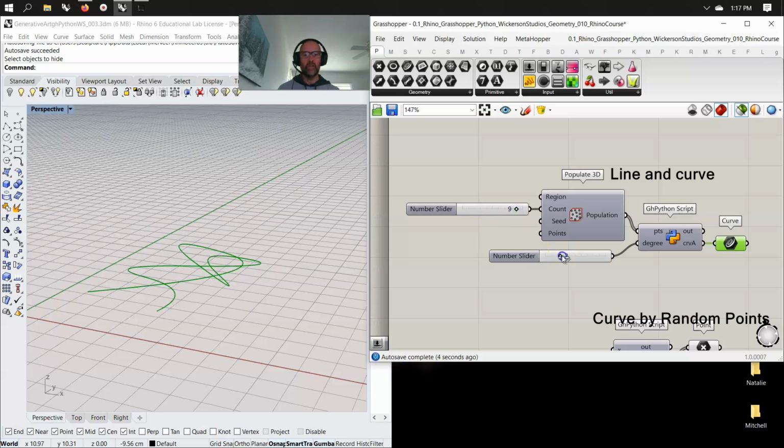And you can also have a degree function in here afterwards in my Python, which allows me to go from polyline to different degree NURBS curves, which are pretty exciting. That's really about all the way up to degree 5. So degree 1, 2, 3, 4, 5, and you have an effect on that curve. And that beats going in and having to make the Rhino script, add polyline, add curve, and add interp curve. You can just do it all in one function.